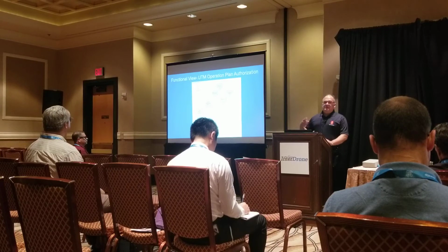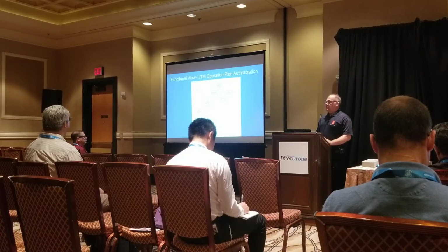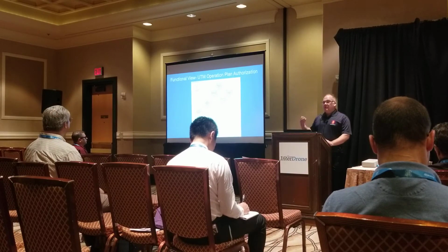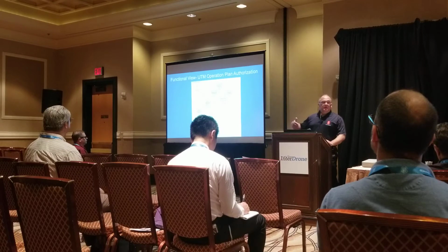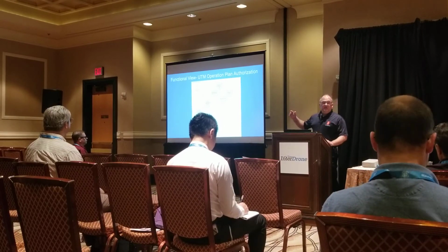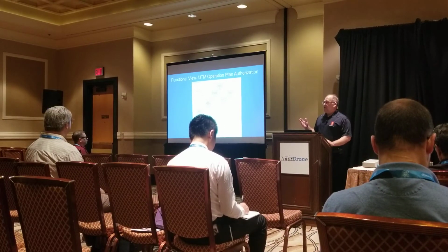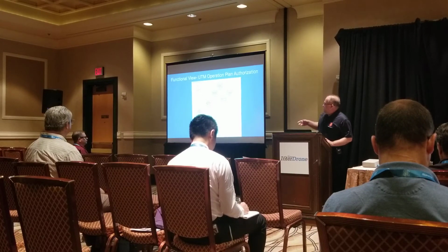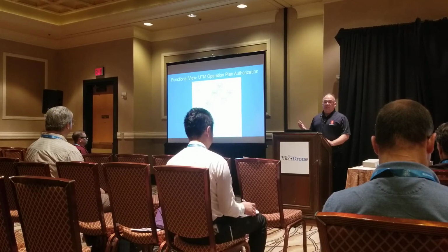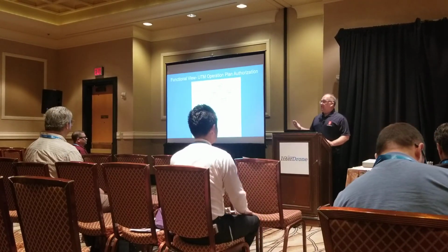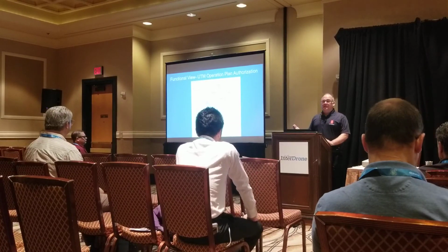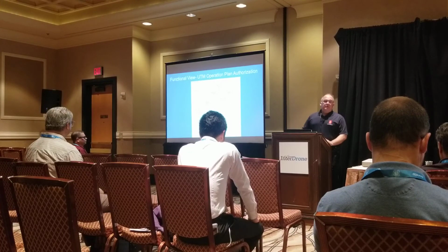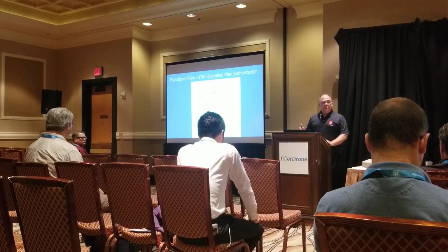However, there's the edge cases that we talked about. What happens when it doesn't meet those rules? Well, now it has to send that information to a UTM operator and say, is this acceptable? UTM operator may or may not accept it. And if they do reject it, we need to have the information going back to the mission planner saying, it's rejected, and here's why. In addition, there might be an instance where the UTM operator looks at it and says it's not in compliance with regulations, in which case it needs to go back to ATC. Potentially, if the UTM operator isn't comfortable rejecting it, thinks that maybe this is okay, then there's an interaction with ATC as well. Make sure that they're okay with this.